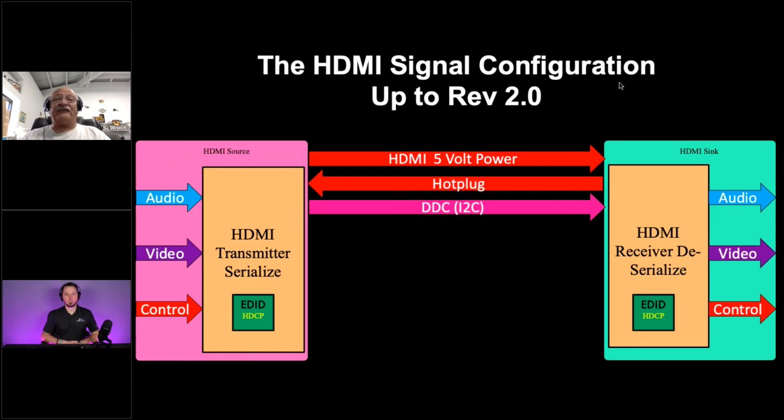And Philips, they have a spec just for that rise time. And it's tight. It's a very tight spec. And so if the wire's not made right, or let's say they put those wires too close to the outer shield, at 100 kilohertz, the capacitive loading of the shield will suck that information into the shielded ground.